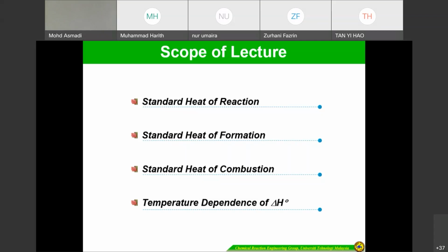Gasification sometimes uses two stages. Pyrolysis is sometimes a part of gasification. The target of gasification, the product, is the gas, rather than liquid. But there are many types of pyrolysis, whether slow, fast, or flash. If slow, our target is generally the solid, and for liquid we use flash and also fast pyrolysis. It depends on the heating rate actually.